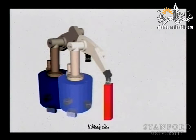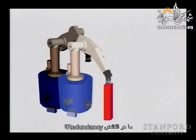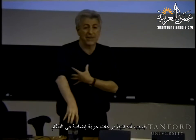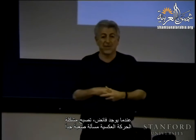And this is one of them. You can imagine the robot is going to move to that configuration. But the problem with this is redundancy. What is redundancy? Redundancy is the fact that you can reach that position with many different configurations because you have more degrees of freedom in the system. And when you have redundancy, this problem of inverse kinematics becomes a really difficult problem.